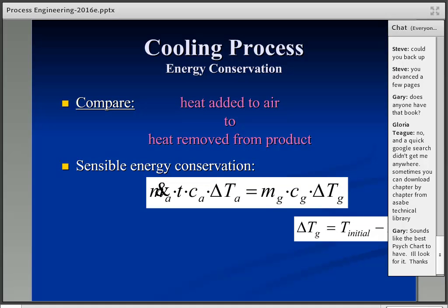The other thing I have in here, we've hit 8 o'clock. I had an evaluation of the cooling process because you can be drying this material or cooling it. So you do the same kind of balance for energy in the cooling process. We had a drying process. We did the mass balance, do the same kind of balance on energy. Look out for my ampersand here where we had another M dot that didn't get done, and you get this energy balance just like the mass balance we did for moisture.